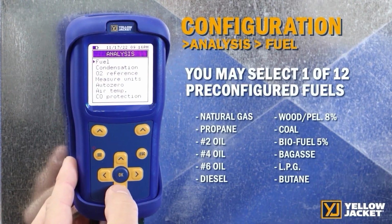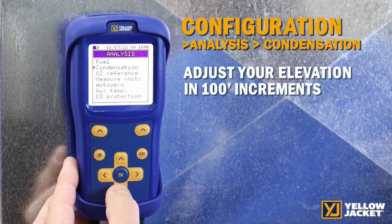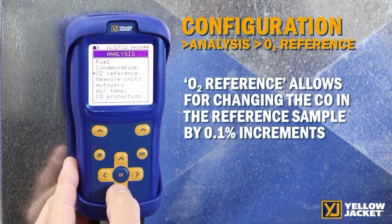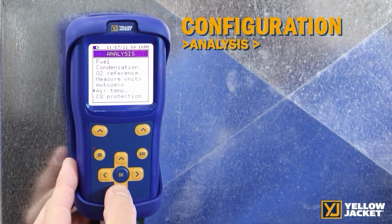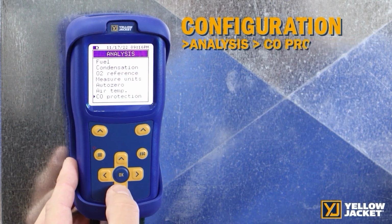In the Fuel menu, you have the option to select one of 12 preconfigured fuels. Condensation allows you to adjust your elevation in 100-foot increments and adjust relative humidity for current weather conditions. O2 reference allows for changing the O2 in the reference sample in increments of 0.1%. Measure units allows you to change units for CO, pressure, draft, temperature, and altitude. Air temp allows you to match the actual air temp sensor variation to recalibrate the zero mark for temperature changes.